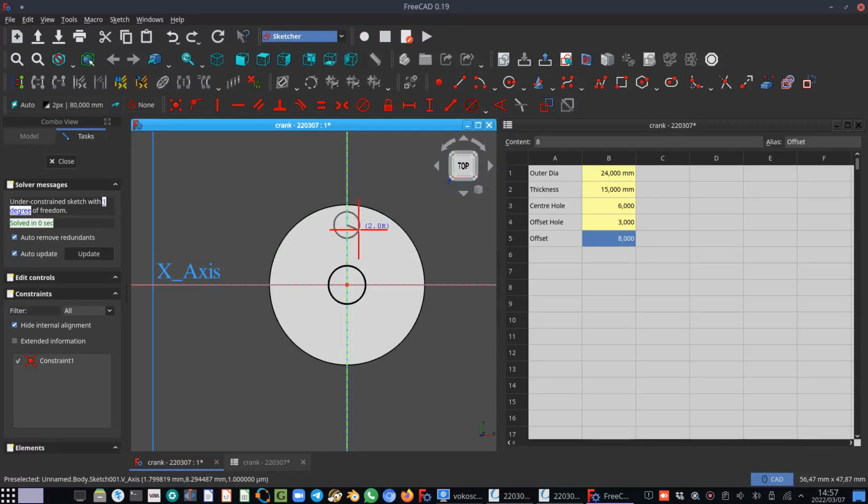I drag it out, I click again, and there I have my 2 circles. And here you can see the fixed point to an object constraint is active. I call it tangent or coincident. It's not really coincident, it's more tangent to the line that we've selected. Okay, so there are our 2 circles.